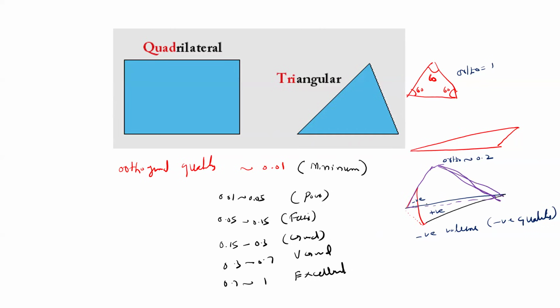So now it will get confused whether this edge should be common or this is going to be with this edge. So it will get confused, and you will have a hard time getting data from one cell to the second. So this will always go to divergence immediately. Okay. So negative volume is not required. It's not possible for CFD.